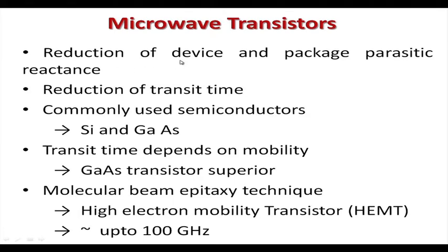Now, obviously, compared to small low frequency transistors, microwave transistors will need to reduce the device and package parasitic reactance, because we have explained that otherwise it will create problems for everything. Also, transit time of the device should be reduced, since the frequency of oscillation in the microwave region is quite high. So, the transit time of the carriers should be reduced much.